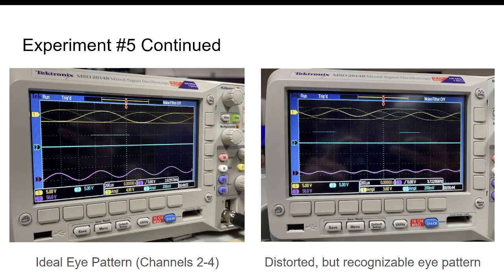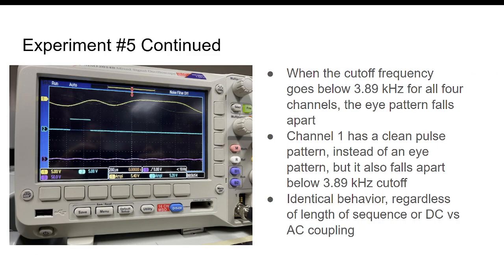And then we see that as we manipulate the frequency of our low-pass filter, we get some distortion, but our eye pattern is still recognizable. Now, when we cut off the frequency below 4 kilohertz, we get something that's not an eye pattern, and that's very bad. This is how we can showcase that manipulating the frequency does mess up our results.